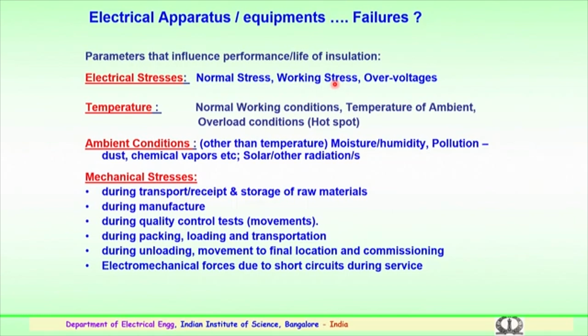Also during unloading, movement to the final location, and commissioning or erection of these equipments. In several places these mechanical stresses have to be considered and proper measures undertaken to see that the insulation or the equipment is not mechanically stressed.